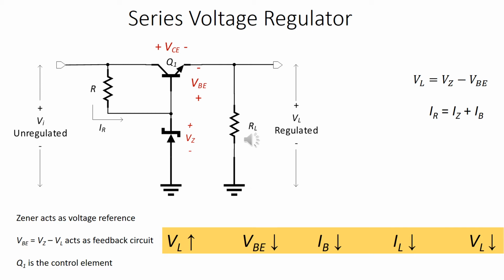Let us see the first circuit diagram of a series voltage regulator. Let us try to compare it with a Zener diode regulator we learned in power supplies. In the normal Zener diode regulator, there is a series resistance Rs between input and the output. In this diagram, we replace that series resistance with a BJT.